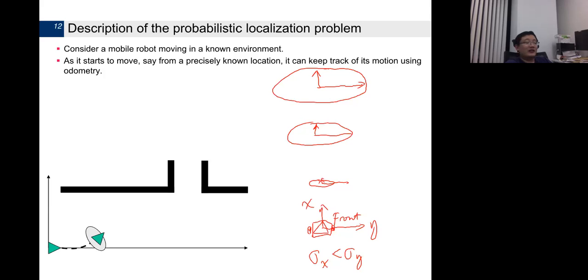This is caused by the motion of the wheels, because this uncertainty purely depends on the motion of the wheels. If you have two wheels moving in one direction, often one wheel may be stuck or floating, and then the uncertainty in the Y direction will be much bigger. Once the left wheel is blocked, the robot will turn left.